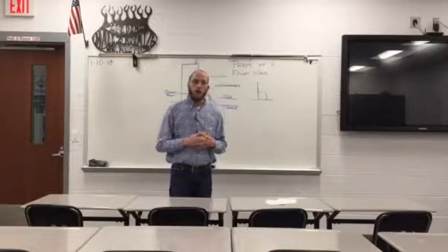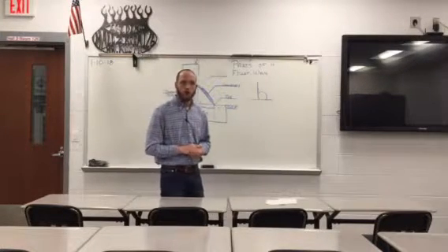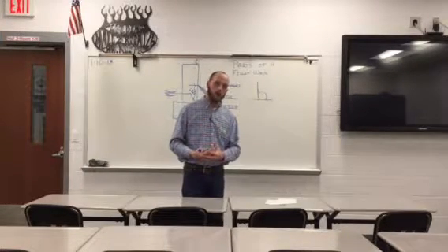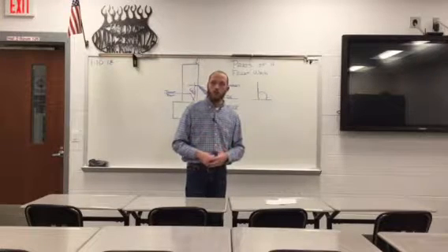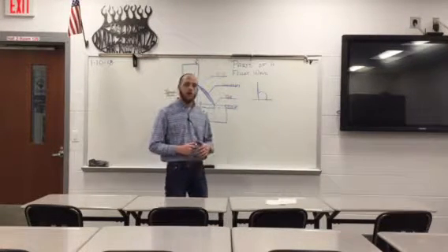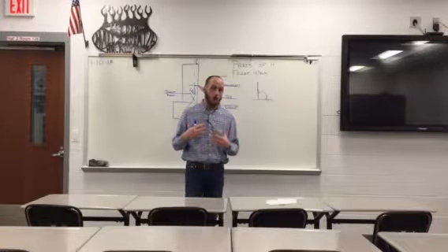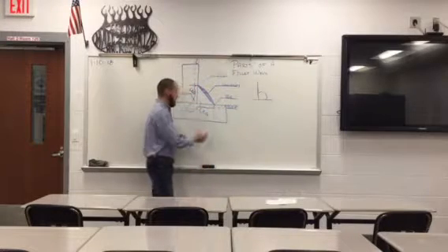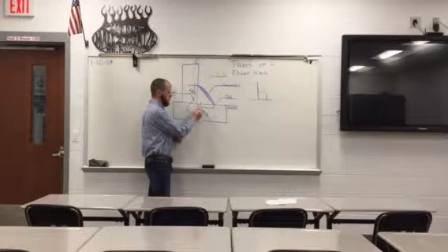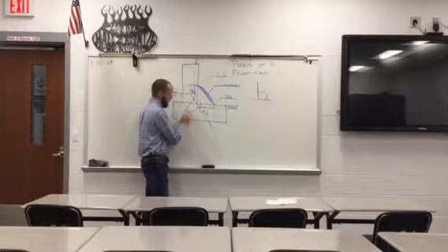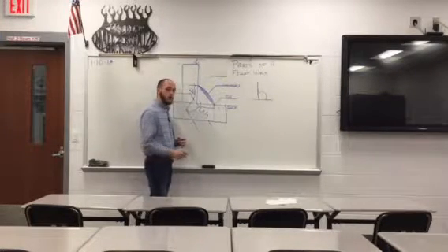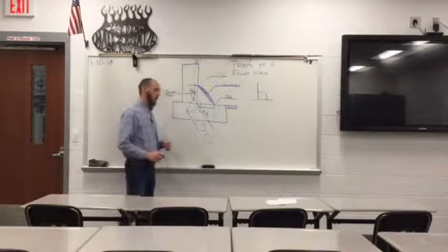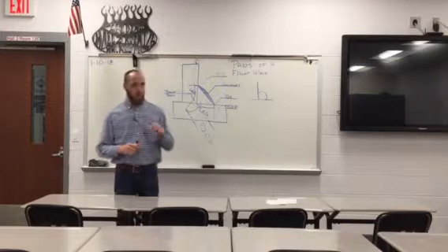The difference is that depth of fusion is how well the entire weld fuses or bonds to the existing base plate, and depth of penetration is how far that weld metal burns into the base material. Depth of penetration is measured from the joint root to where the weld metal stops extending into the joint root or the base material, and that is our depth of penetration.